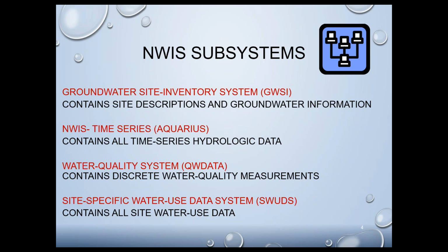The field computing software will take the data entry, for example, the water level measurement, the method, the reference points that you are using, like the measuring point that you use, a description of the accuracy, all those pieces of information. It will transform that data entry into what we call a transaction file. Then that transaction file is a simple text file that gets pushed into the database.